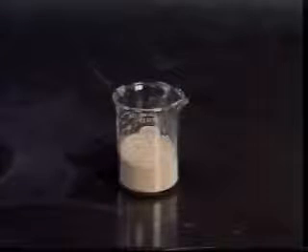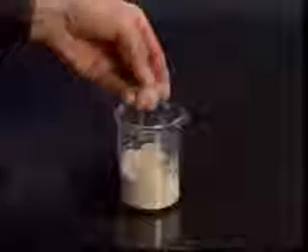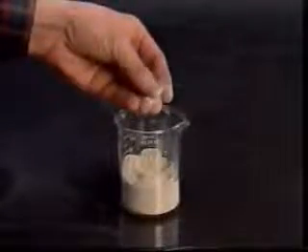Viscosifiers are added to a drilling fluid to improve its ability to remove cuttings from the wellbore and to suspend cuttings and weight material when the mud is not circulating. Clays and natural or synthetic polymers are the materials most commonly used. The most common clay additive is bentonite, a fine-grained clay mixture which is mostly made up of Montmorillonite clay. Bentonite, also called gel, is added to freshwater-based muds to improve the mud's ability to remove cuttings and also to improve its filter cake forming capability.